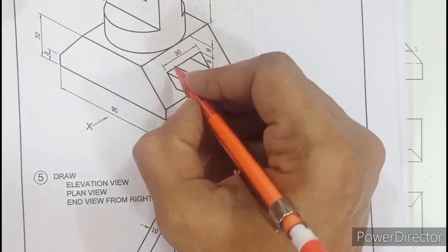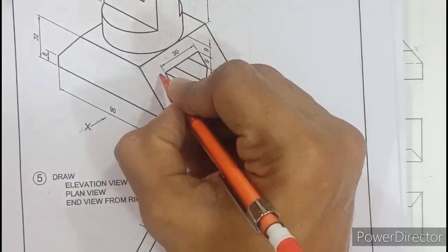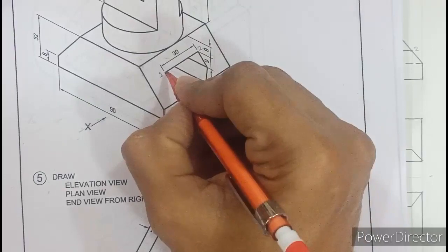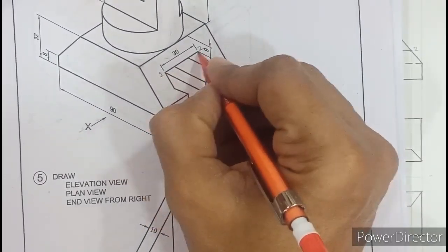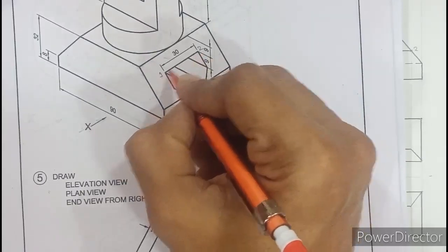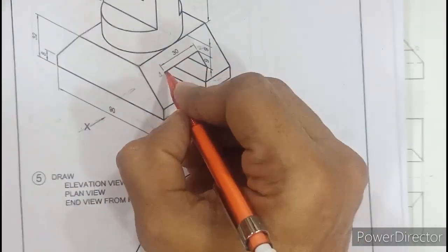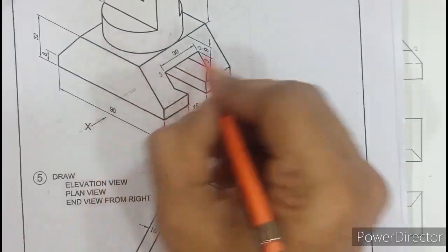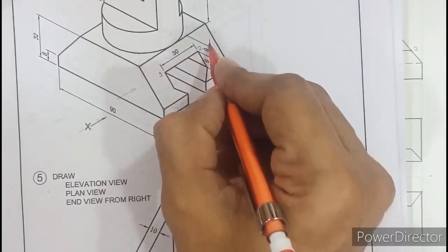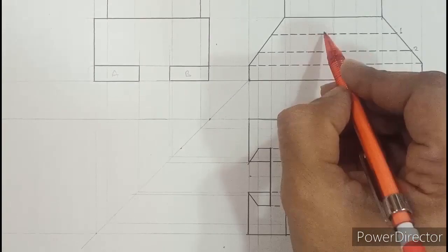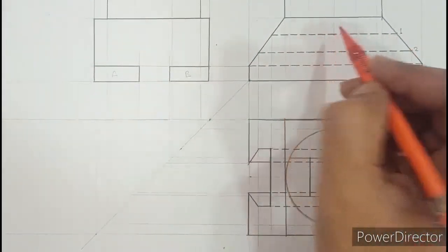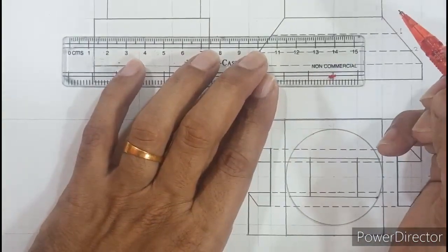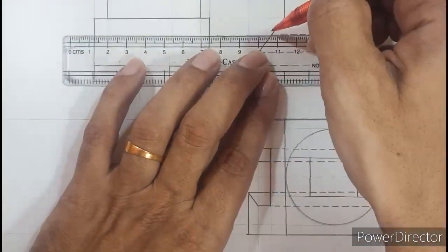So let us see in the side view, if I need to draw line 1, 2. So suppose 1 is here and 2 is here. The width of the line is 30 millimeter. So you need to recognize this line from the front. So if you look in the front view, 1 and 2 will be seen as a single line, and that is 9 mm from above. So in the front view, we have already drawn a hidden line representing 1, and that is 9 from above. So this hidden line, I need to project it in the side view, and I know that 30 should lie